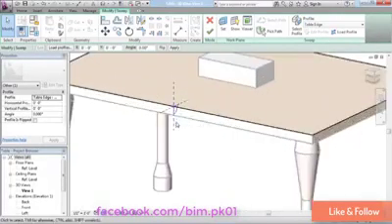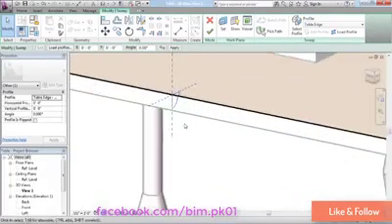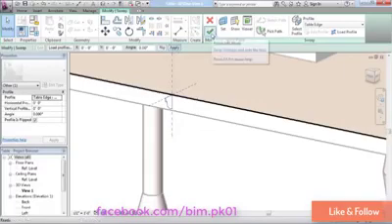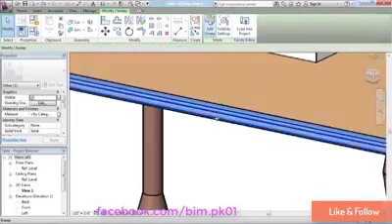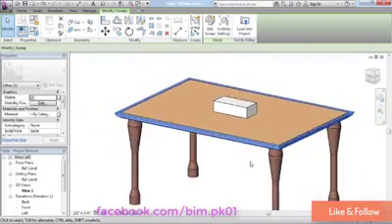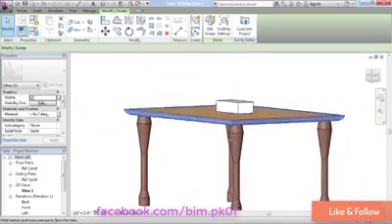And if I zoom in here, you can see that I intended this one as a subtractive edge. So it's oriented within the thickness of the table family. Well, for this first demonstration, I'm just going to flip that because we're treating it as an additive edge, as a molding that we're tacking onto the tabletop. So let me go ahead and do that. Click Apply, click this Finish button right here,